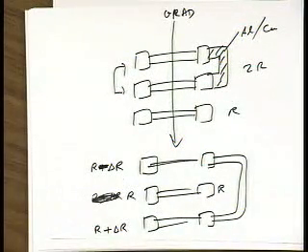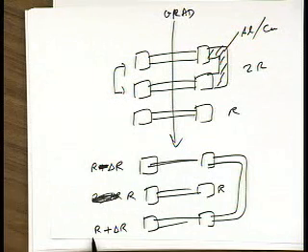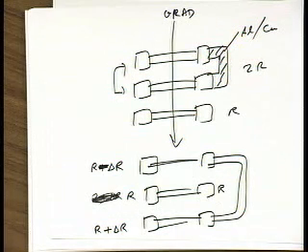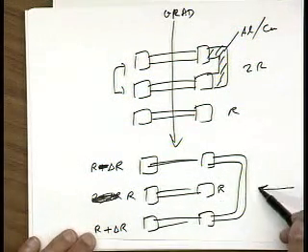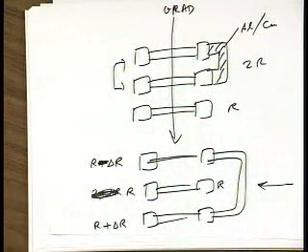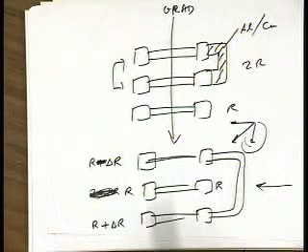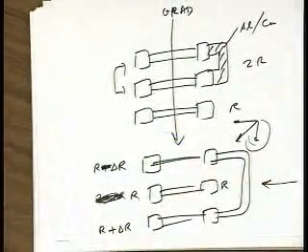Well, you now see that to first order things cancel out because the resistance here is R minus delta R plus delta R plus R. The delta R's go away, and I have a resistance of 2R and R. Okay? And you can convince yourself that this actually is a pretty good idea. It works pretty well. If there's a doping gradient in this direction, it doesn't affect things. It's only a doping gradient in this direction that affects things. And for any gradient, I can decompose it into two gradients, right? And it's only this component that matters. So this layout technique is actually pretty nice. It allows us to design very precise resistor ratios.